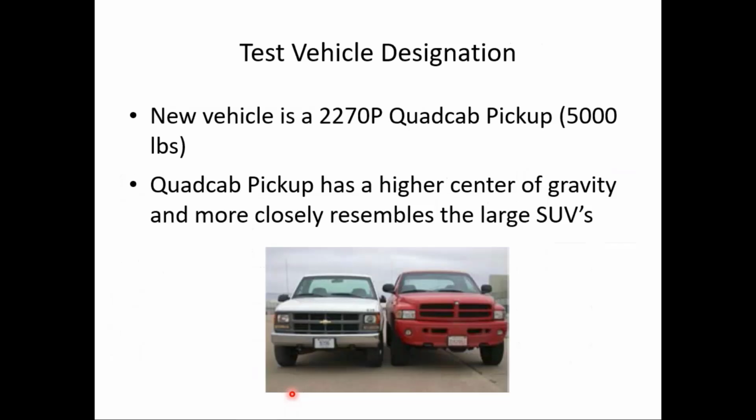But just as an example, you see here on the left the white pickup truck, that was maybe the design vehicle in earlier versions. Now we're talking about even larger pickup trucks, or, as I said, maybe even moving to EVs because of their weights. You can see not only are they larger, but notice the bumper height, and the bumper height is critical in terms of striking the guardrail, the barrier itself. So not only weight is important, but also bumper height, or center of gravity, I guess we would say.